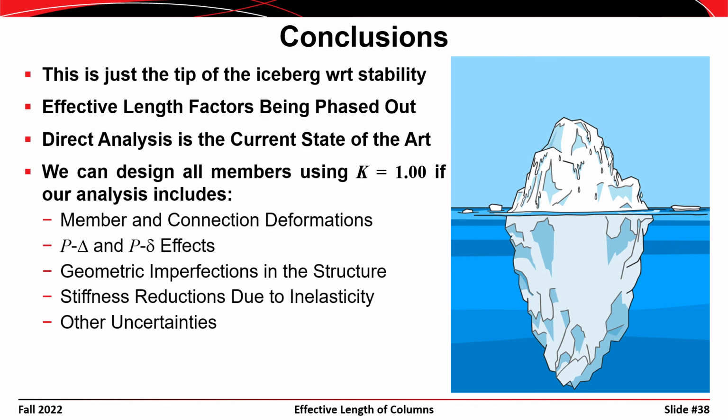I expect that within the next 10 to 20 years that effective length factors will likely be eliminated from the specification entirely in deference to the adoption of the direct analysis method for all frames.